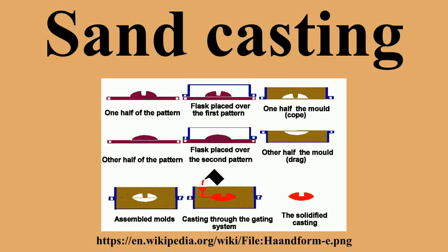Unlike the name suggests, green sand is not a type of sand on its own, but is rather a mixture of silica sand, chromite sand, or zircon sand, 75 to 85%, sometimes with a proportion of olivine, staurolite, or graphite. Bentonite, 5 to 11%. Water, 2 to 4%. Inert sludge, 3 to 5%. Anthracite.